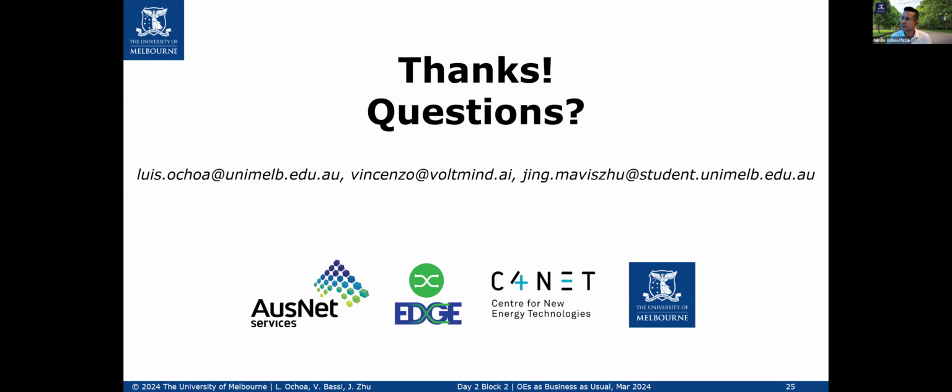Vinny, there's a question for you. Can you answer it? Yeah, starting from Gary Hayes, right? Do you need 100% of smart meters or can a lesser level be used? Well, as I presented at the end of the presentation, we have proven that up to 15 to 20%, we can still produce usable results. Of course, there might be less accuracy, but up to 15 to 20%, we're confident to say, and we are investigating for lower